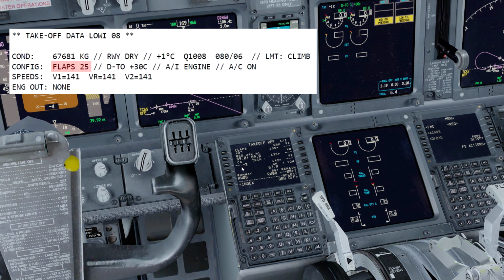And the center of gravity, normally you would get it from the load sheet, but in this case you can let the 737 determine itself what the center of gravity is. So it's 26.1, and we're gonna set that right here. And as you can see, the aircraft has now calculated some V speeds itself. You can also check the ones on the flight plan.